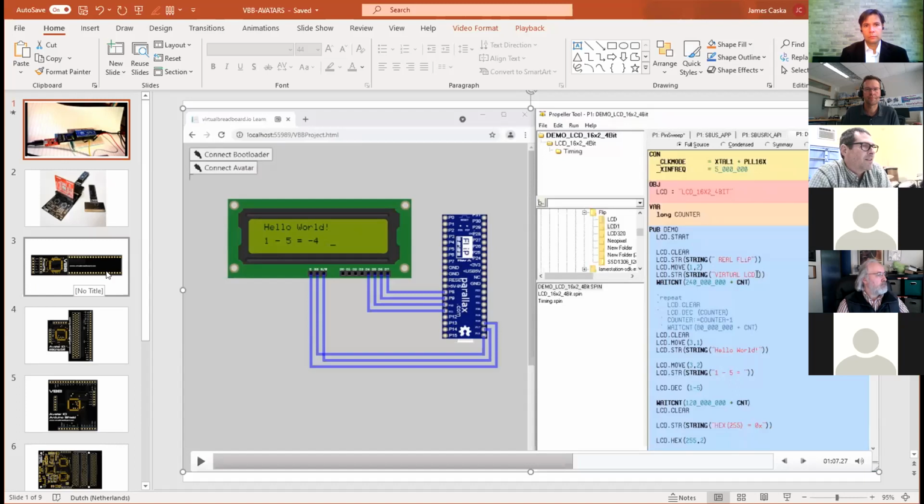But unfortunately, the P1 just wasn't fast enough. I could only ever get like 8 megahertz SPI, and the default application was the Arduboy, so I wanted to capture the Arduboy SSD display in full speed at full frame rates.